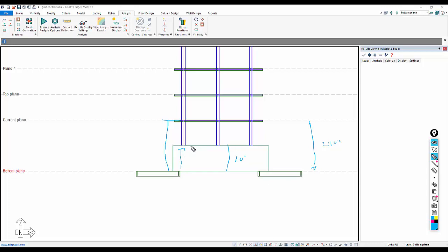In this type of a setup, the program requires the use of columns to be stacked on these beams. So if you needed to simulate, for example, the load transfer through more points other than just these three, then we might have to put in a series of columns to represent better distribution of force down into the beam versus just some discrete points where we have the columns modeled. We have the beam here. Let's go and take a look at that beam.